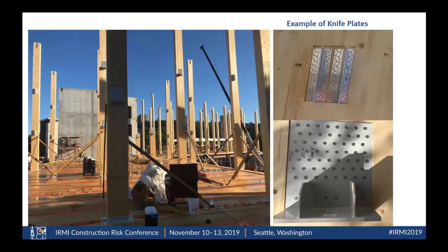And then the second thing is trying to figure out the connections. When you have concrete standards, ACI standards, and steel standards, the tolerances of concrete and steel are greater than that of wood. We had to come up with some way to overcome that, and it was a universal connection detail with knife plates.